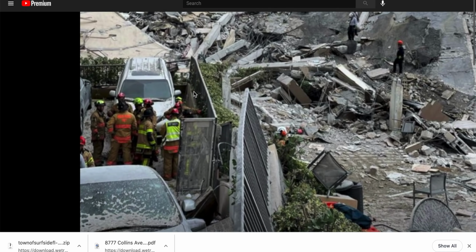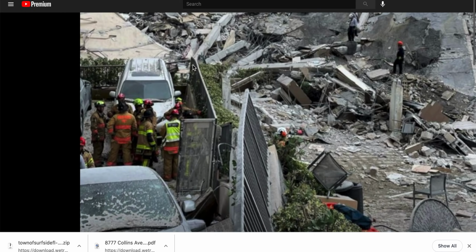So we have this dropping straight down, this deck here. Like I said, looks like an elevator ride it took down. You can see the top of the steel is bent a bit, so there's a little torque action on the back side when this part collapsed, or secondarily collapsed, and slammed the deck and pulled the rebar and pulled down on the back of the deck a bit there.